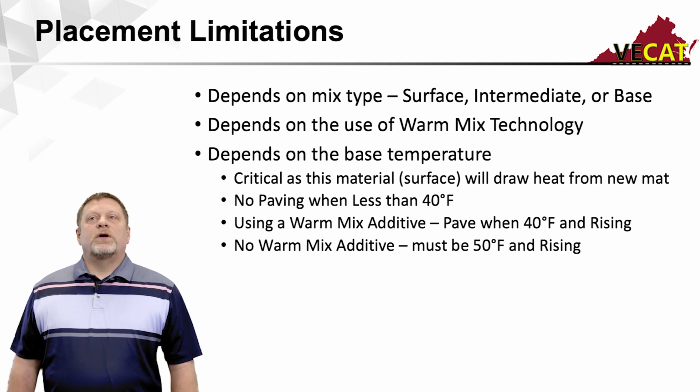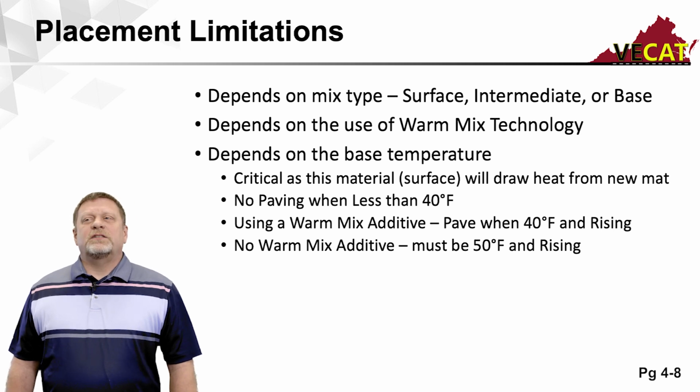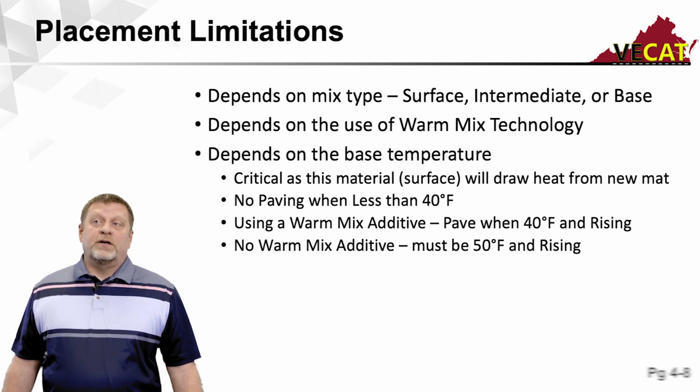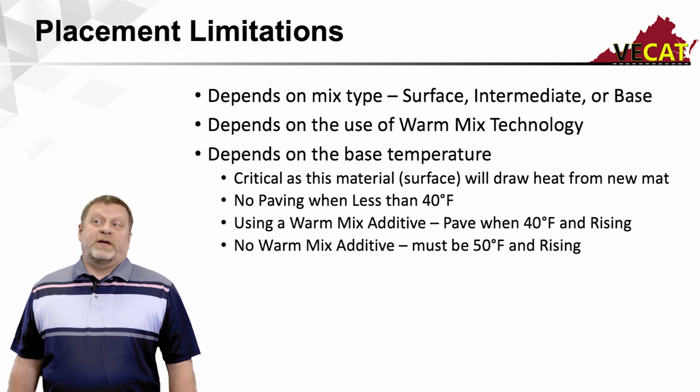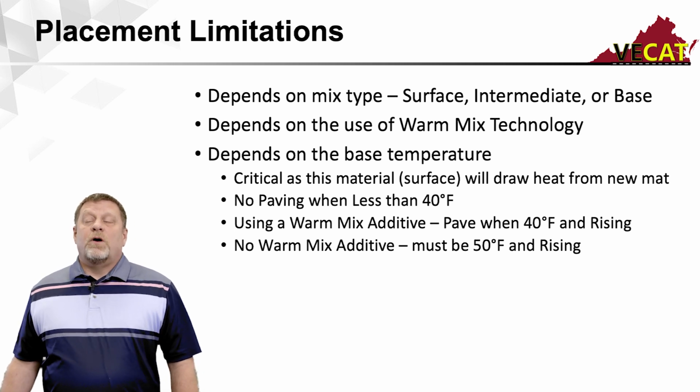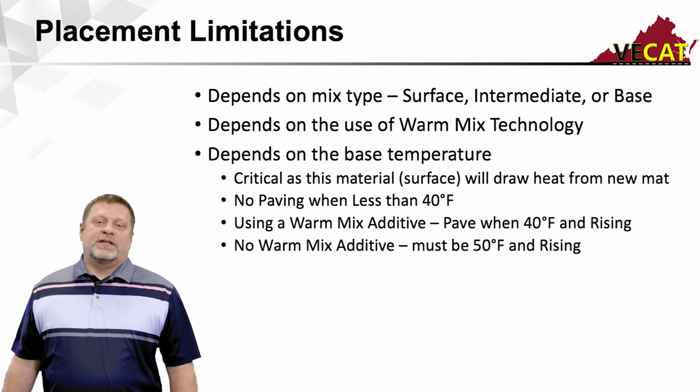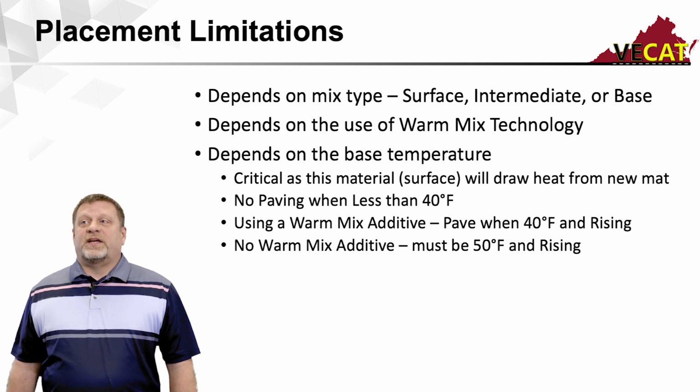Now let's move forward and talk about some placement limitations. There are different variables that can impact our placement limitations. One of the things we have to consider right off the bat is what mix type we're placing, whether it be a surface mix, an intermediate mix, or a base mix. Our placement limitations for each mix are a little bit different, and all that's referenced in our specifications.